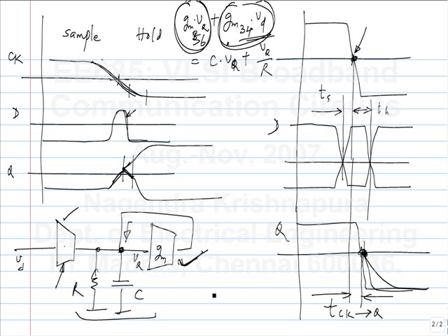And sometimes you do need to do this, because you generally start off with equal size differential pairs for the latching and the sampling, M3, M4 and M5, M6. But sometimes you may have to optimize the setup time or the hold time depending on the kind of data that you expect to see. So in that case, you make one or the other bigger. Anything else? Any questions on any aspect of the latch?